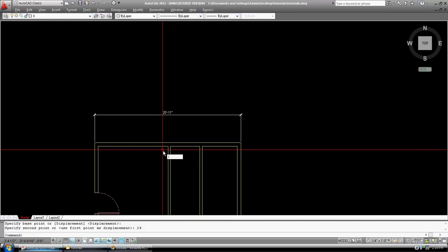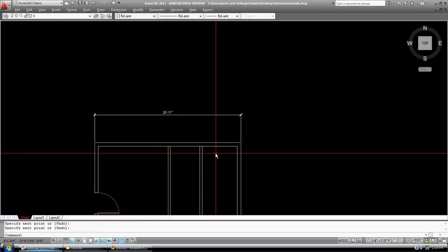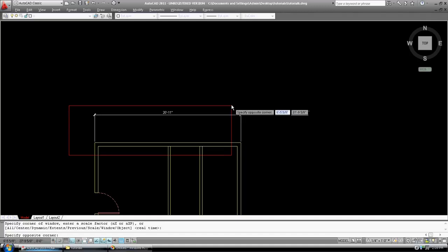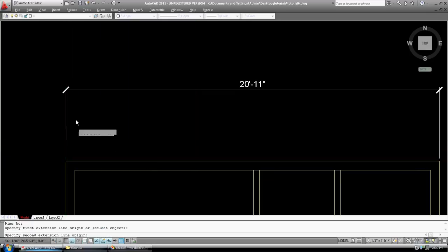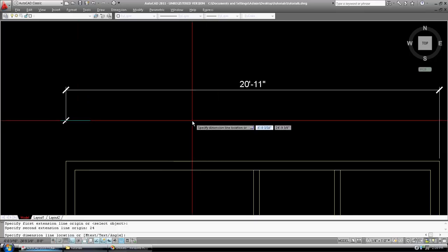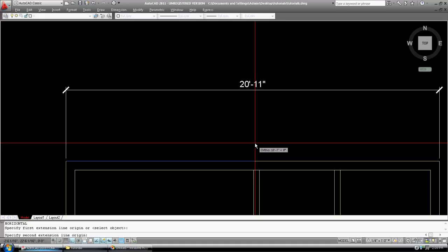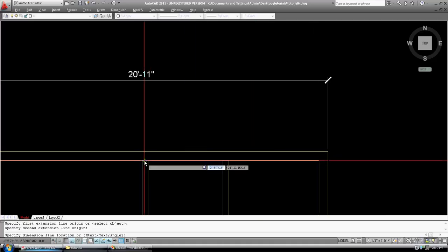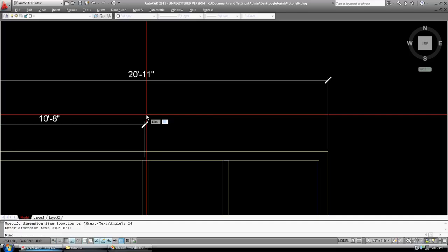but I can also just draw a line from this wall to this wall, and another one. These will be construction lines. Zoom. Okay, which I'll get rid of afterwards, and then I can DIM. Okay, and I can horizontal again. I can start at this point. I can go up 24, enter. Whoops. Let's try it again. Horizontal from this line to the center of this line, and then up 24, enter, enter.